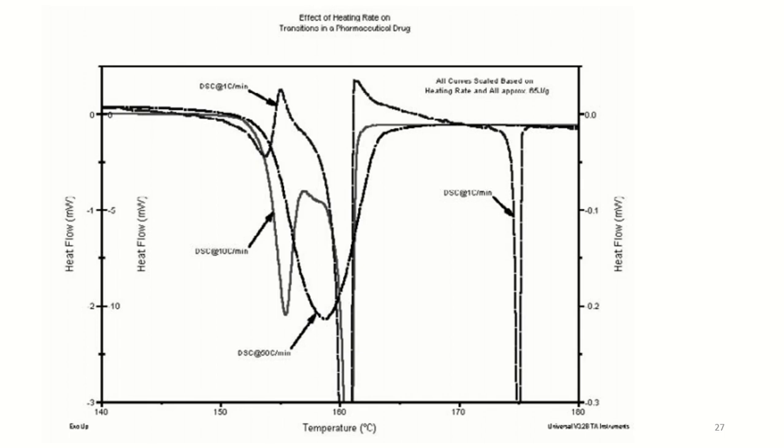At high heating rate, only a single melting peak is seen, which means that there is only one polymorphic form in the original sample. Since it begins to melt at 153 degrees Celsius, as also seen in the 1 and 10 degrees Celsius per minute data, the crystal form in the original sample is the lowest temperature polymorph.